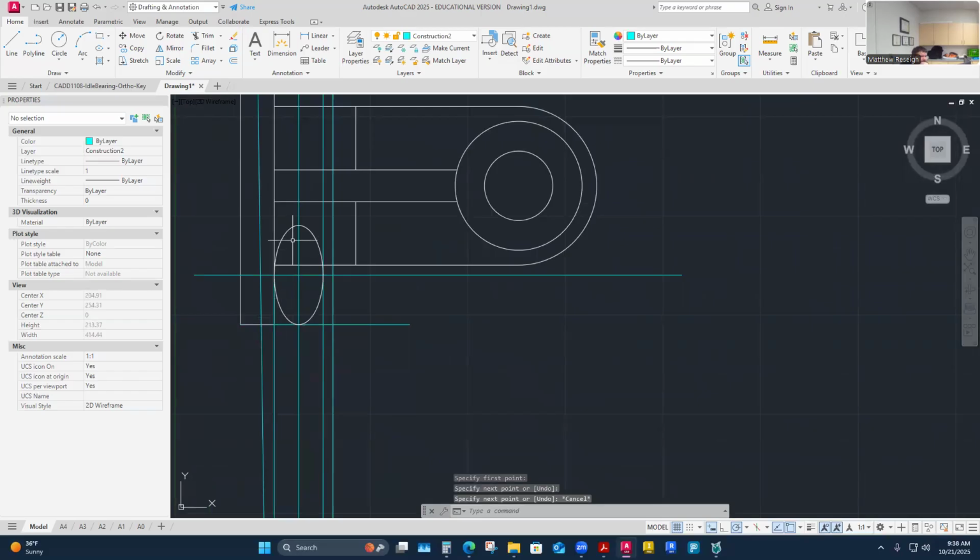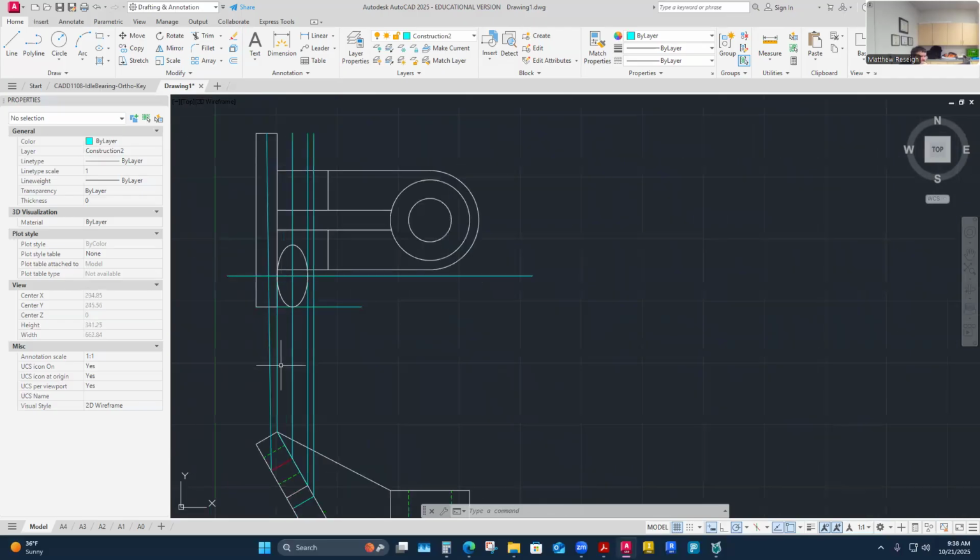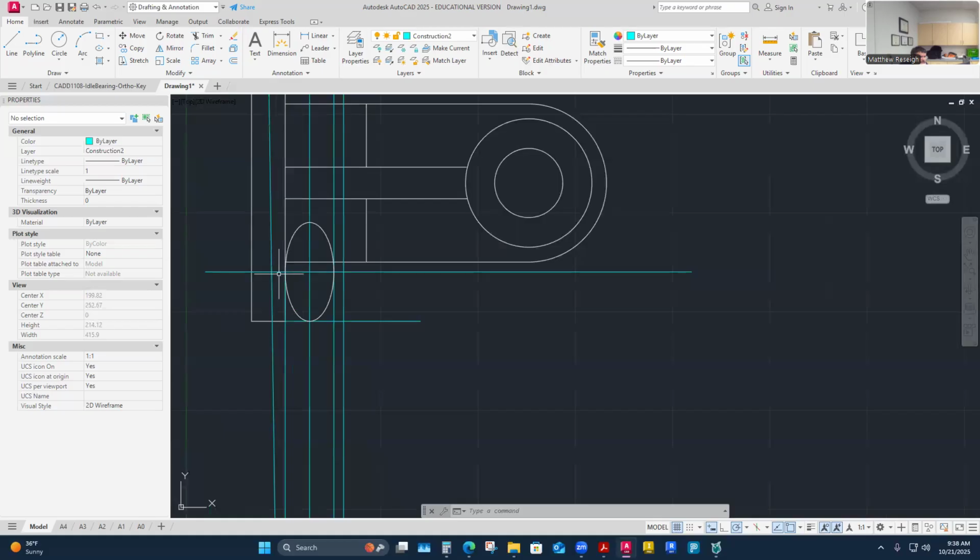Because that's essentially the surface that's towards me in my view, and then I need to know where it exits through there. I can think of the hole exiting through it, or just the physical feature of it. So that's where that one projects up, and I made it cross the same center line. They will be in alignment across this x-axis in the top view.